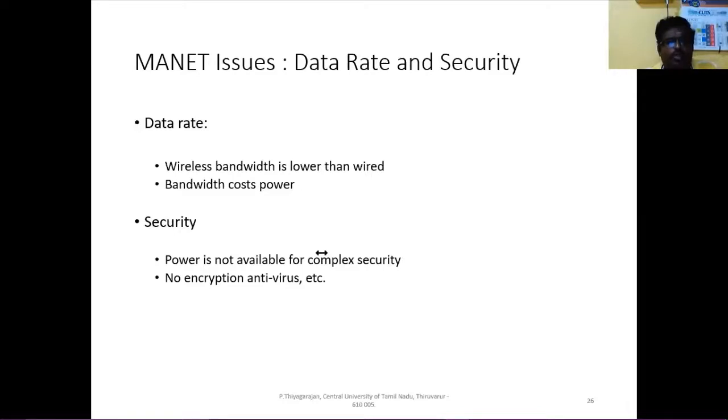With Bluetooth, you can send a video. You can get enough data rate to transmit even video. Now with Bluetooth Low Energy, there is no way that you can send at the same data rate. It uses a lot less power, but you get a low data rate. So the fact that you are going to low power restricts you in terms of your data rate, and that restricts your functionality in a lot of ways.